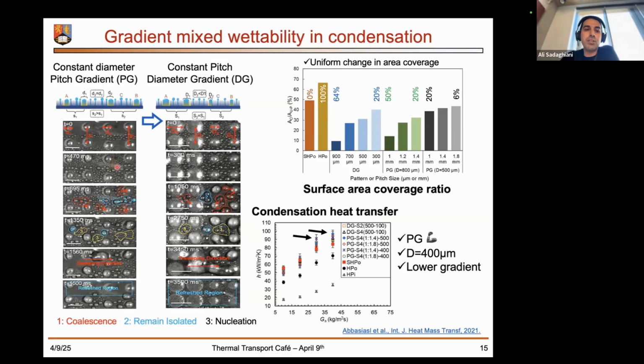So similar observations to the previous can also be seen here. We have the formation of larger droplets on the hydrophobic spots and smaller ones on the superhydrophobic background. Then we have coalescence from the surroundings to the spots, and we have basically mobility on the superhydrophobic background.